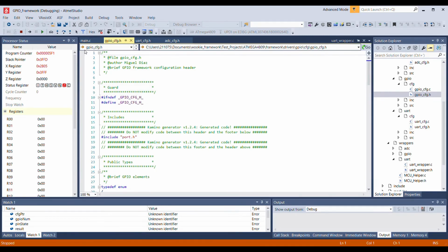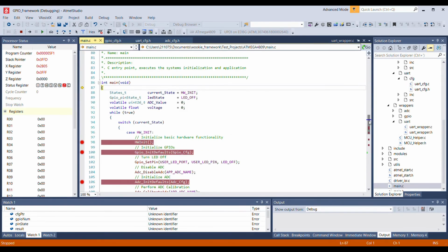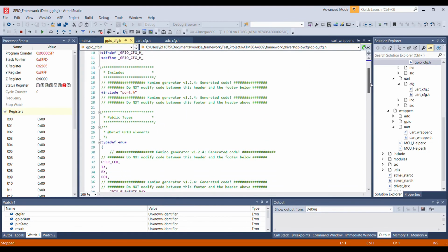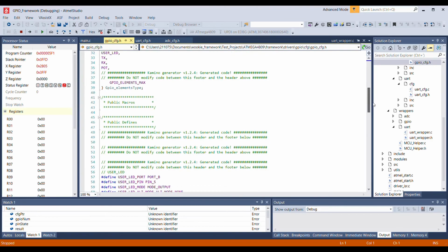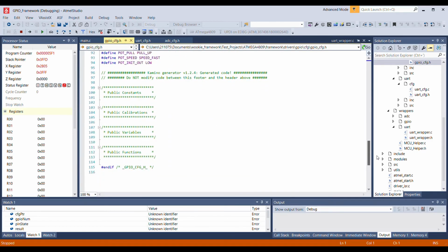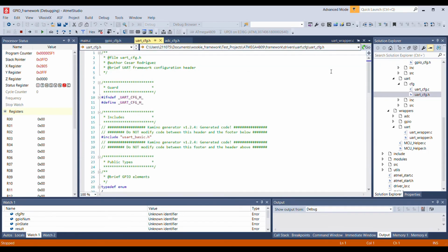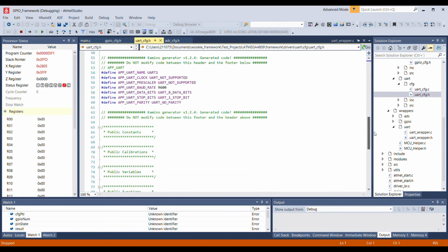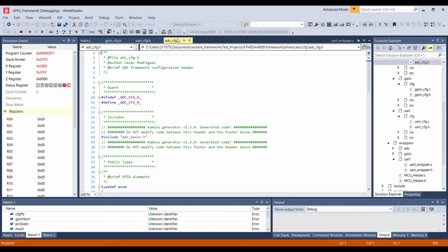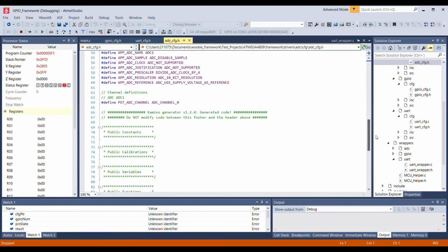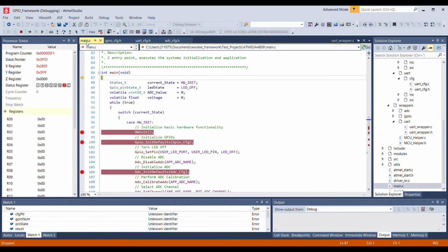And now we can open this code already integrated into our project inside our IDE. In the case of the ATmega4809, we'll be using Atmel Studio as our IDE in order to not only program this code into the board, but also to debug and check that we are going through the framework in order to control the peripherals.